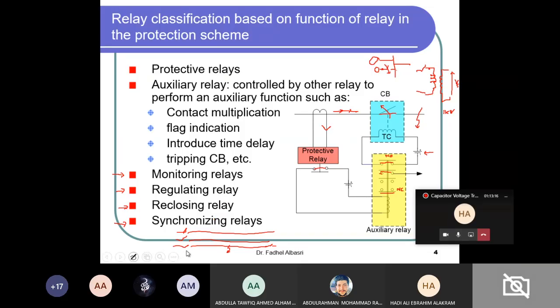Once the protective relay detects this fault, it gives a command to this phase to trip, and it only trips one phase in this case. It's called single phase tripping, or reclosing. So it will open the faulty phase. If this is a permanent fault, once you reclose it, the fault current will occur again, and the protective relay will not allow the reclosing relay to reclose again.